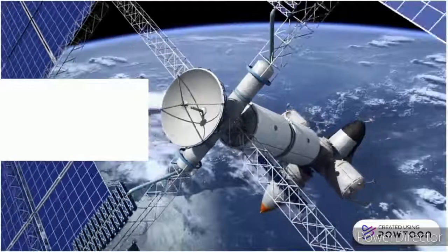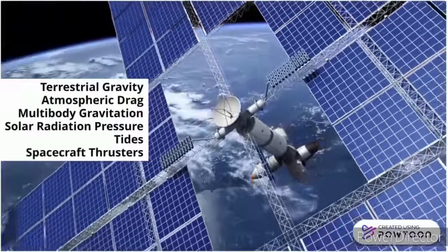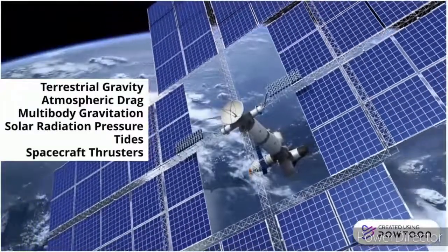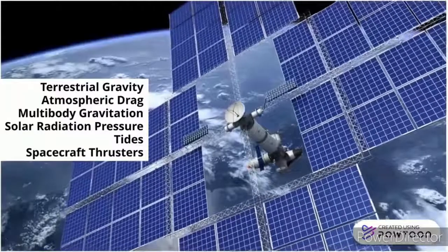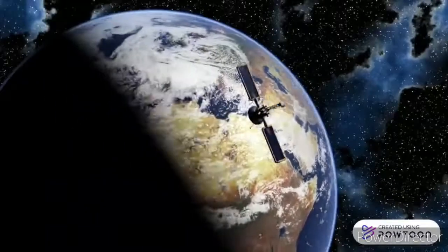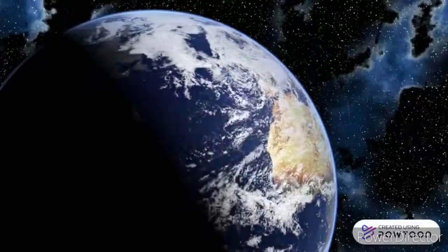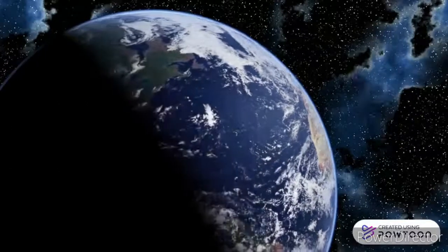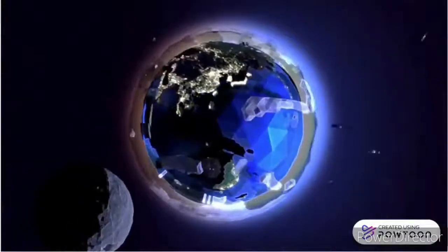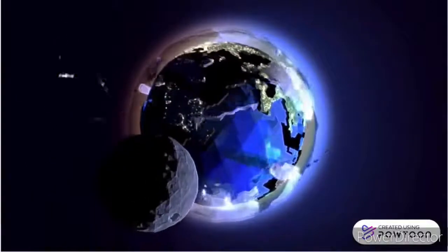External forces such as terrestrial gravity, atmospheric drag, multi-body gravitation, solar radiation pressure, tides, and spacecraft thrusters all have an impact on the satellite. The accuracy and precision required from the orbit determination procedure, as well as the amount of accessible data, influence the forces used in modeling. The nonlinear dynamical equations come from the intricate modeling of these forces.